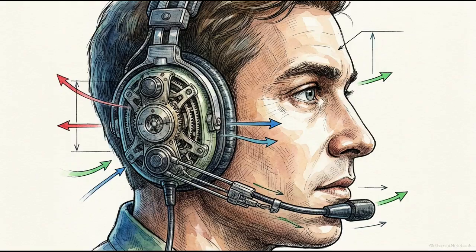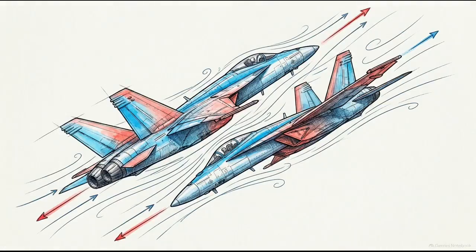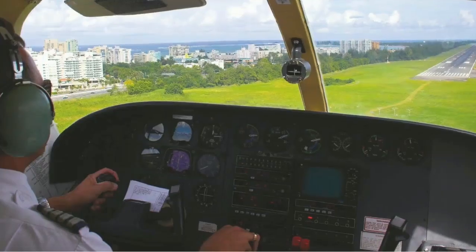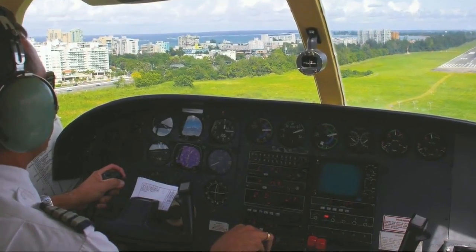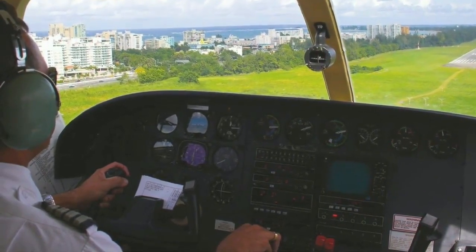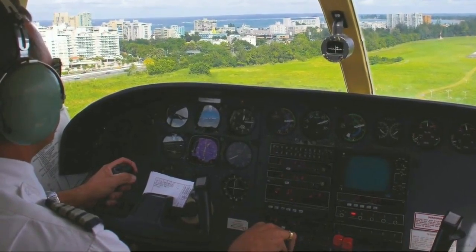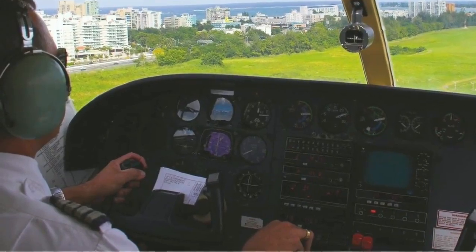Airmanship is a measurable set of skills: subconscious muscular coordination, precise timing during maneuvers, and an intuitive sense of airspeed. The most critical, physical component of this skill is control touch. This is the ability to sense the aircraft's attitude and the aerodynamic forces acting on it through the varying physical resistance transmitted directly through the flight controls.